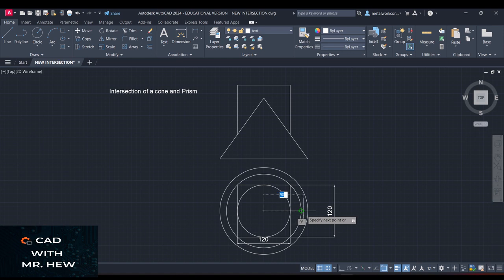All right, so we're going to draw a line there. Enter. Can do the same thing on the other side. Enter. All right. So what we're going to do now, we're going to draw a line from this intersection of this line, which would represent the center line when we're finished, in this circle. Intersect this horizontal. We're going to project a line up to the side of the cone and draw it across, and that will be the largest disk.